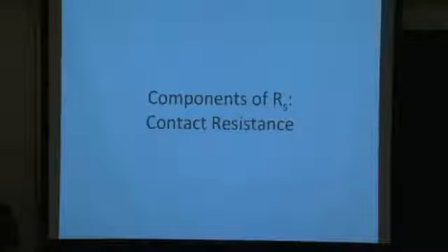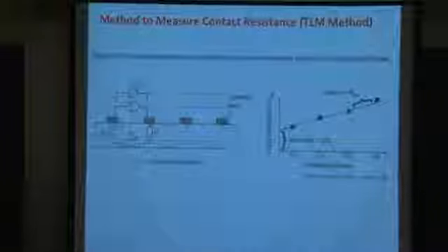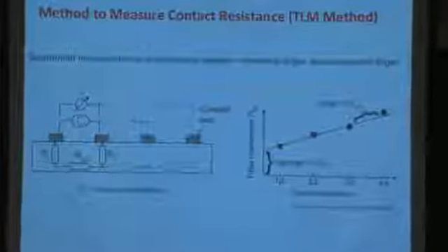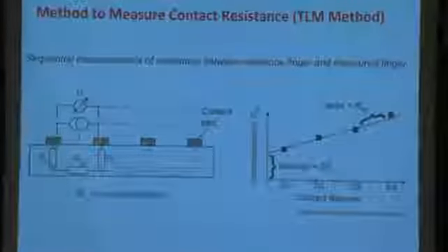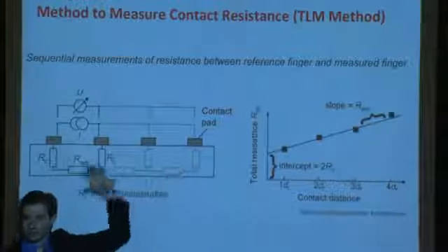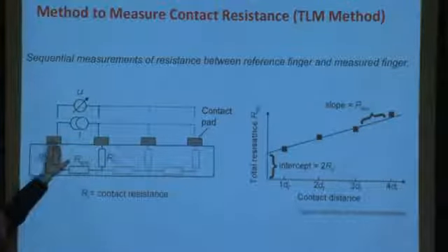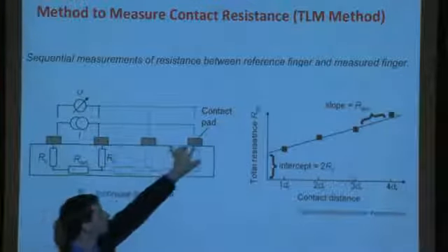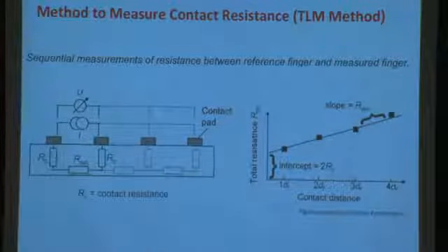Okay. So contact resistance. This is the next thing that can kill a solar cell device. We want to minimize the contact resistance, but the first step to minimizing is to measure, to know what your contact resistance really is. And one simple way to measure contact resistance is to take a cross-section of your solar cell device where you've deposited, say, 4 metal fingers on it, and they're appropriately spaced by some number of millimeters.